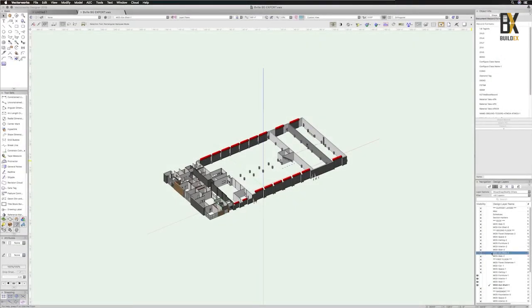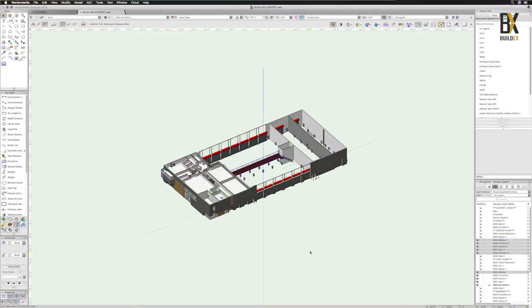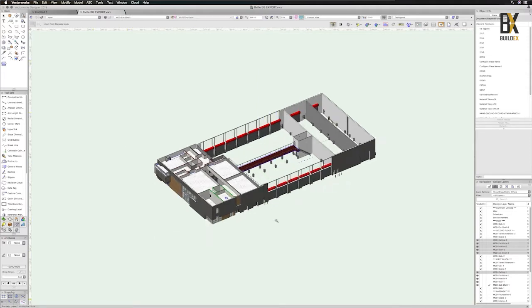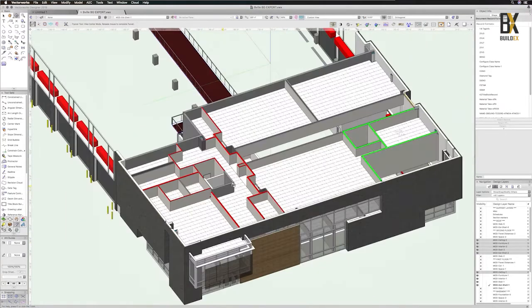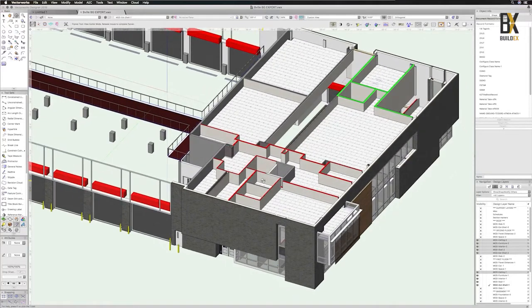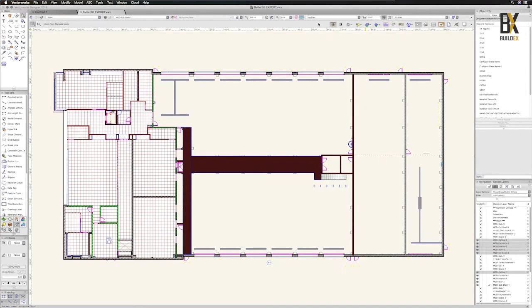Another tip that I can give you before exporting your IFC file is that, using saved views will help you streamline this, but you should have only visible objects, so that when you export, it exports only the information and geometry necessary for the coordination process.